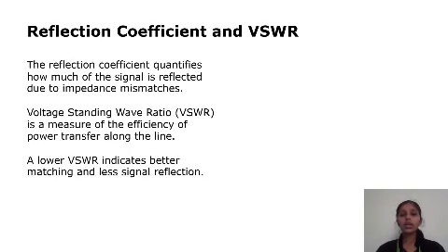Reflection coefficient and VSWR. The reflection coefficient quantifies how much of the signal is reflected due to impedance mismatches. VSWR stands for voltage standing wave ratio, and is a measure of the efficiency of power transfer along the line. A low VSWR indicates better matching and less signal reflection.